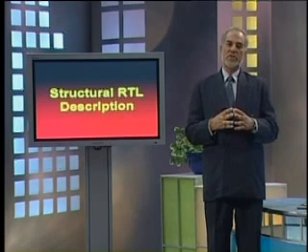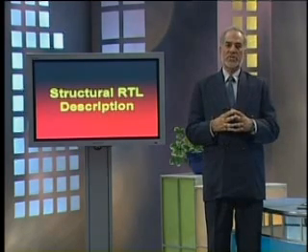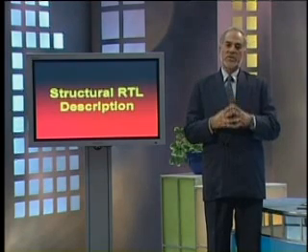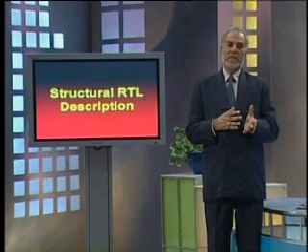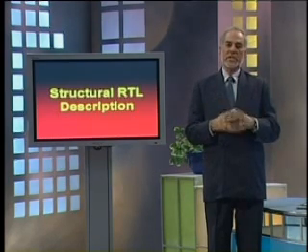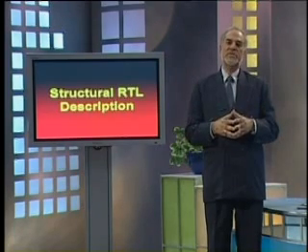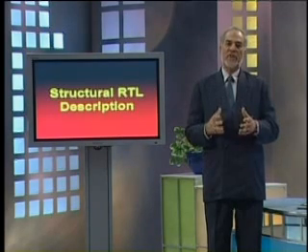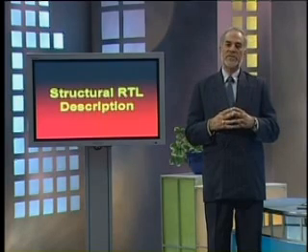We discussed the first functional group in the form of arithmetic and logical instructions with some examples, then load and store instruction, and then we went on to our branch instruction. Last time we ended up with our discussion on conditional jumps, and we said that in the case of conditional jumps, the variety in Falcon is more as compared to what is available in our simple RISC computer SRC. And we have a possibility of usually a near jump with a limitation of the constant. You might realize in this case altogether we have 16 bits in the instruction set and a maximum of 8 bits to define the constant, which would give us an effective address to which one needs to jump with reference to the present contents of the PC.